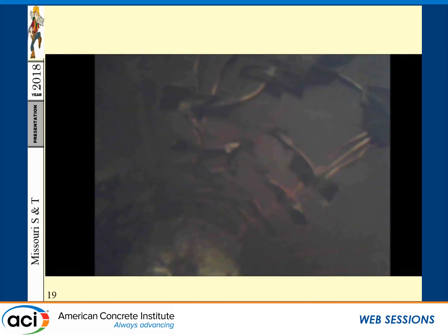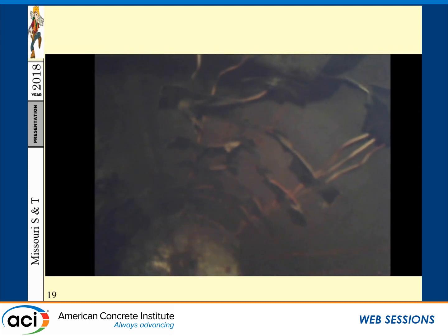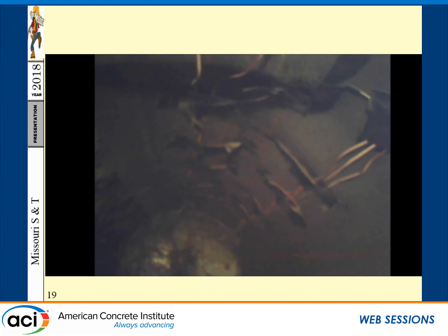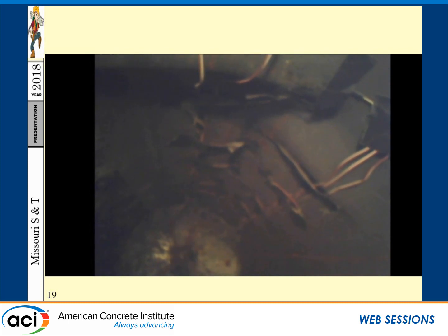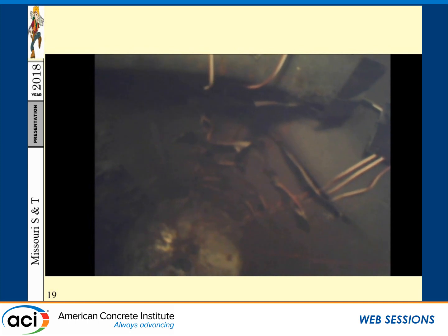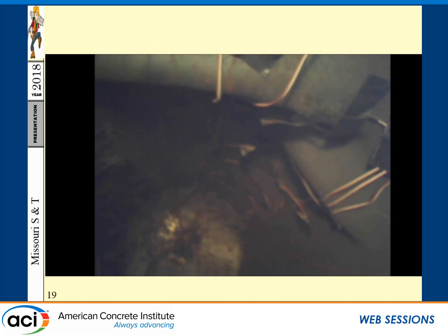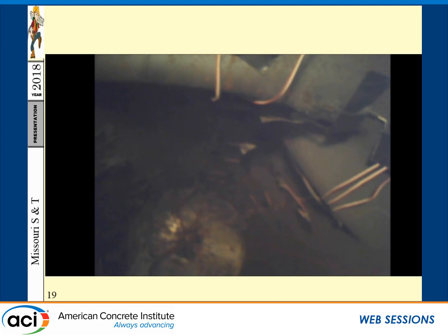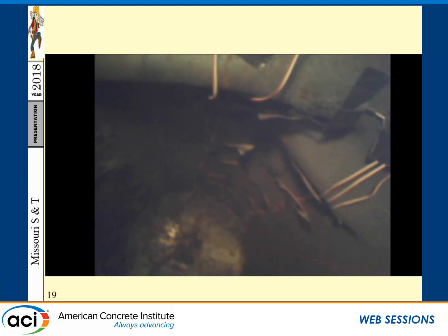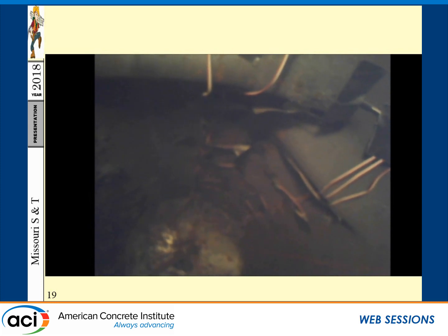So we inserted some telescopic camera inside the columns, and the goal here is to see how the column is from inside, how the steel pipes are working. So this is the surface of the pipe, and this is the bottom. So we are looking from top. So this is the surface. You can see here the corrugation. This is just the compression, buckling of the steel pipe. You see over here all this folding. You see the steel buckle. However, once we start to remove the loading, you would find release of all these buckling on the pipe.